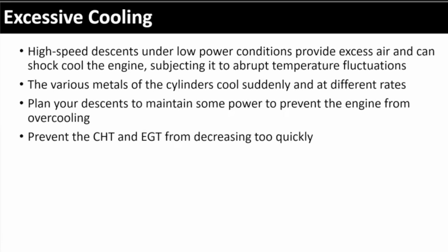Make sure you're not overcooling. Some aircraft will have in their pressure and temperature monitor gauges a light that flashes or some indication that says you're shock cooling. You're getting cooled too fast, right? Slow it down a little bit. Okay, so hot is bad. Cooling too quickly is not good either.